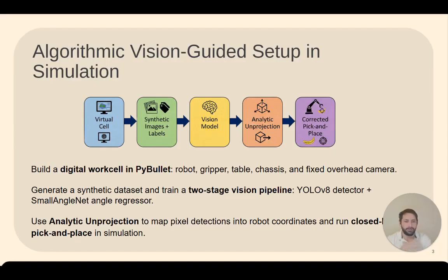So basically, we're trying to translate the coordinates of the camera to coordinates that the robot can interpret, and then it can do the feedback. This is very important because when we take a picture, the camera output is in pixels. So we need to translate that, and also the coordinates of the robots are different from the camera. It can be interpreted in the robot, and also not in the base frame, but because the robot has a gripper, it needs to be in the tool center point, which is our TCP. And when the camera sends that data, it needs to be interpreted in robot millimeters. So this is something that we can do in the virtual cell with AI.